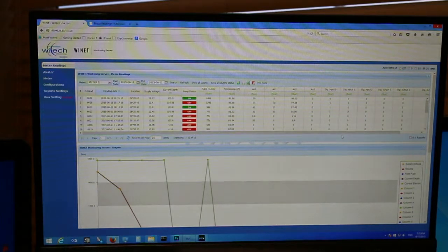Now, in order to save energy and save data over the air, we can configure the unit. Let's say you're only going to have analog 0 enabled because you're only going to see a pressure, but you're not going to use analog input 1, 2 or 3 on the unit. We're going to see that later with the device manager. You can configure the unit to only read analog input 0 and not read everything else because you don't have anything connected there. So you disable these 3, and once you disable those on the unit, those are going to disappear from here.